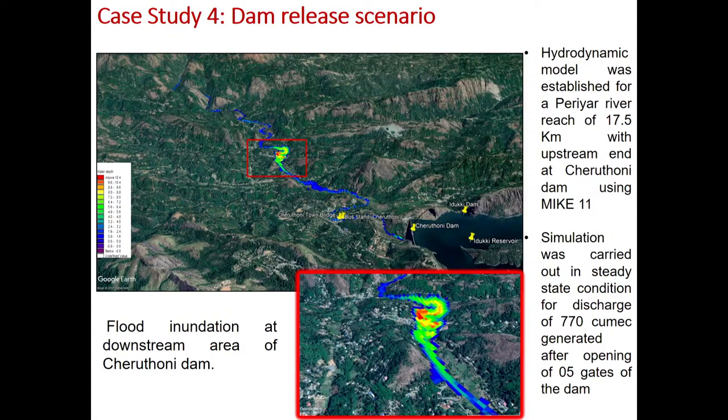Again, there are different methods for how you can generate those different hydrographs, or synthetic hydrographs, from that glacial lake. So that also you can look into. But if you don't have the bathymetry data, there are empirical equations where they try to link the features or characteristics of that particular lake with the volume. Like they try to relate the area of that lake with the depth, or the area of that lake maybe with the velocity, and then you approximate a certain volume of that lake, and based on that you generate the hydrographs. The same hydrographs you again route using hydrodynamic modeling.